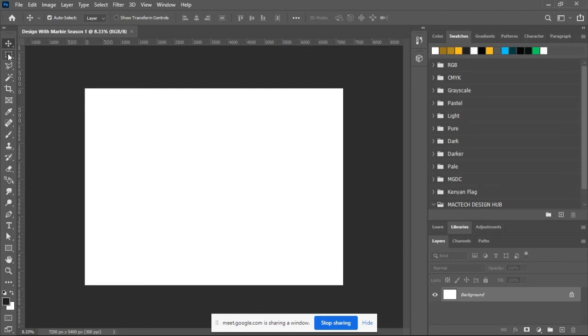And then the next tool right there is a polygonal lasso tool. When you're using a polygonal lasso tool, you'll be able to make selections in your own maybe custom shape, a square, what, but it's up to you to decide what kind of selection you want, the shape of that selection. And right below it, we have a magic wand tool. It selects similarly colored image areas. You will find tools which are pixel based.